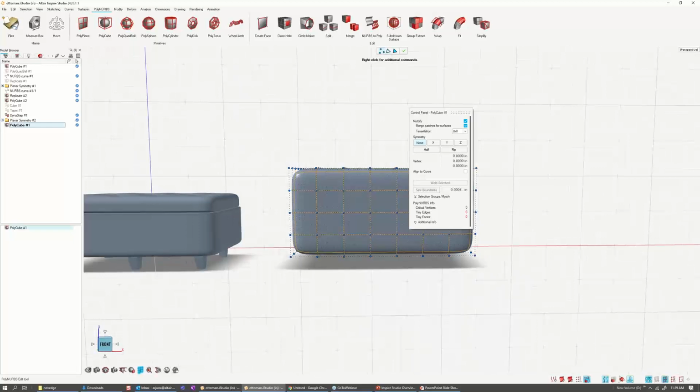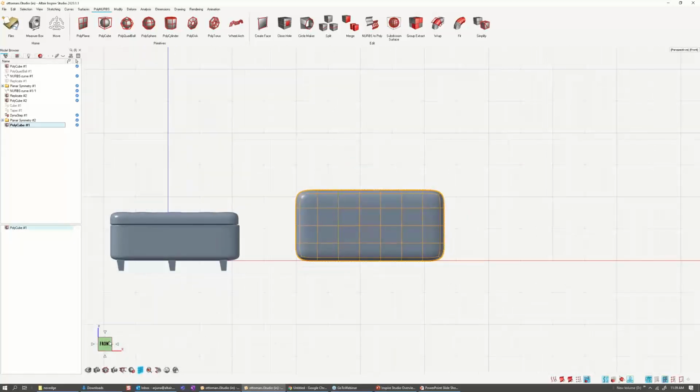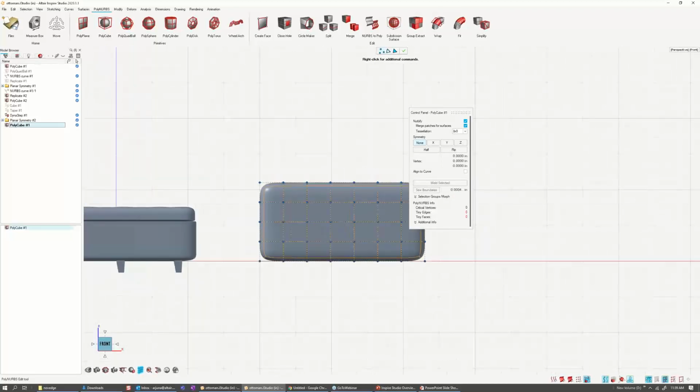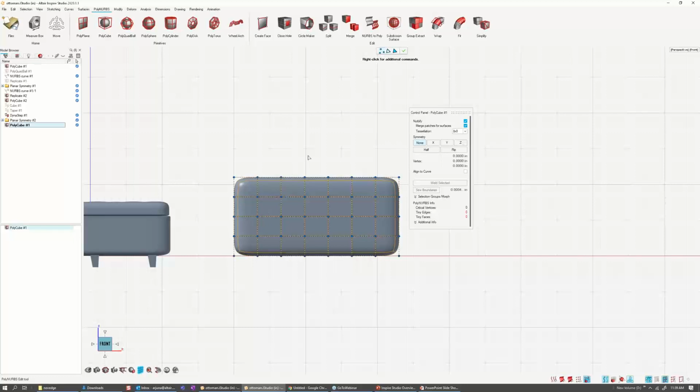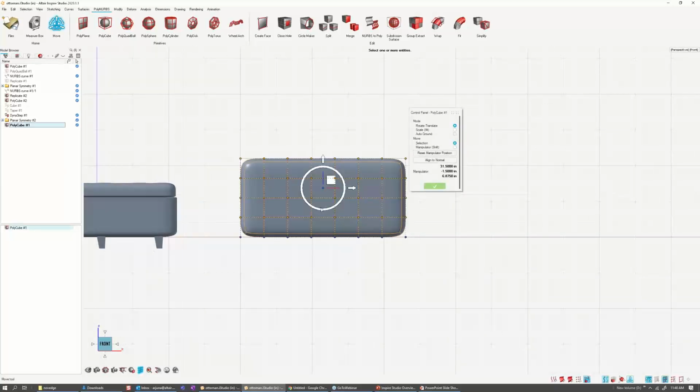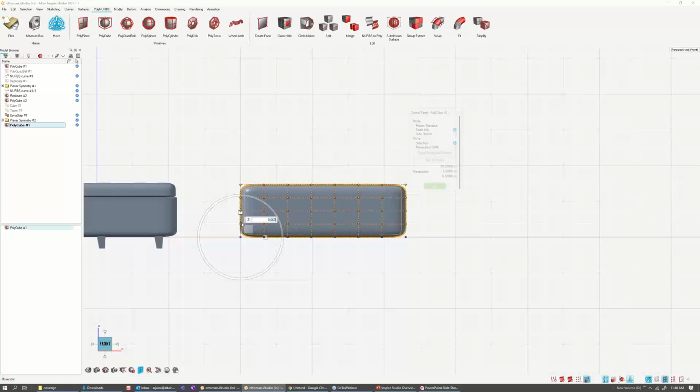And again, as I showed you before, I can scale this object if I want to change the shape. So the bottom is on the ground, but the top seems to be very, very high, very tall. So let's just change it a little bit. So I can just select all of the points that I want to scale. So I can select all of them, hit W on the keyboard. But if I scale it, it'll probably scale around this point. So I'm going to hit Shift to move the manipulator first. I'm going to click and drag it here because I want to scale it down from here. Once I'm done with this manipulator moving, I hit Shift again to come back and go to Scale. And I can just drag it down this way to change the size. So let's make it 0.6. And right click swipe twice to get out.